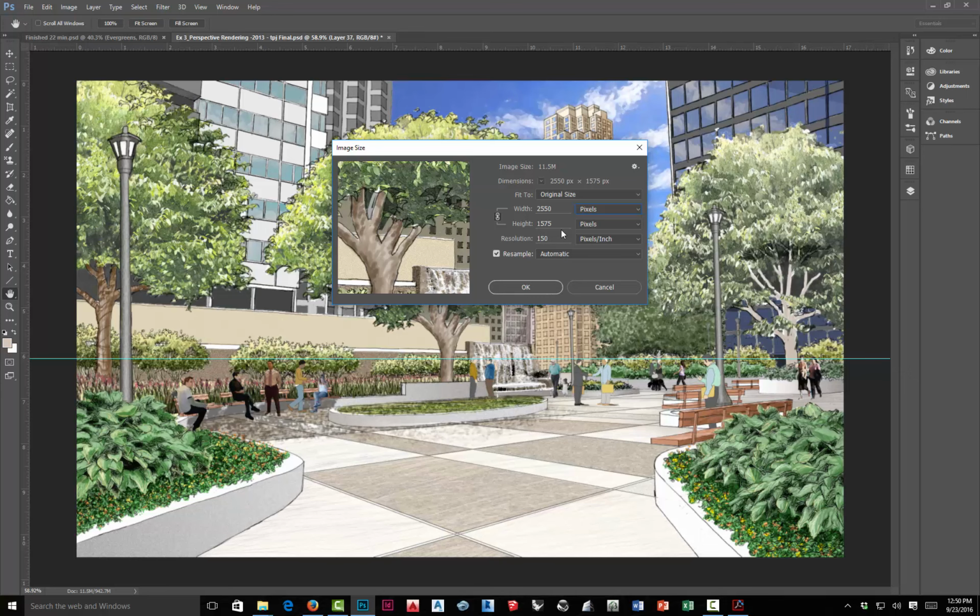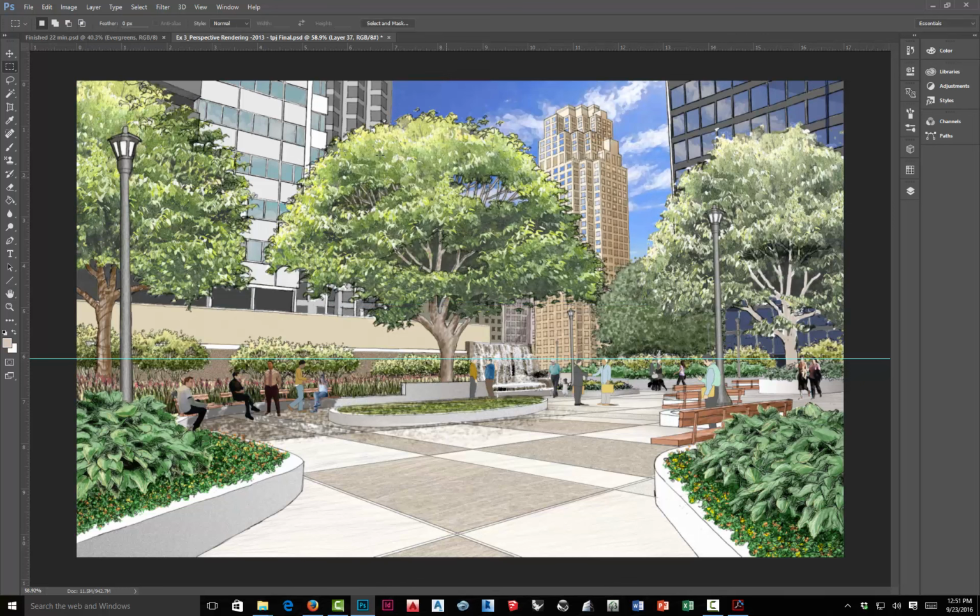So that gives you the ability to output a bigger picture, but it doesn't necessarily improve the image, or it does actually allow for a little more detail as well. For most of the things we work with, 150 pixels per inch will be good. Anything lower than that really isn't high enough resolution. Anything higher, you don't really see the benefit when you print it. And on the screen, you can't display it that high. So basically, that gives us a good average, and we'll talk more about that as we get into working on exercise 1. So I'm not going to belabor that point right now.